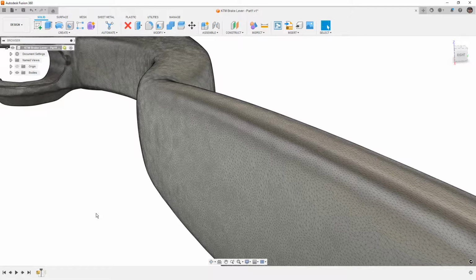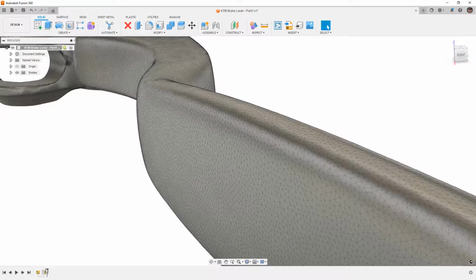In this case, I ended up using one of the higher smoothing levels, and the reason for that is because this is a well-used cast part. It doesn't have perfect features, it doesn't have prismatic fillets on the corners, and leaving it in the raw version really wasn't going to help me much. So I did bring it in. It was smoothed out in the Einscan Pro software, and it was remeshed here. And the main reason for that is we're going to talk about whether or not we even want to remesh it.